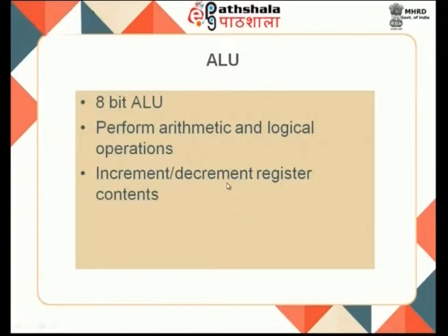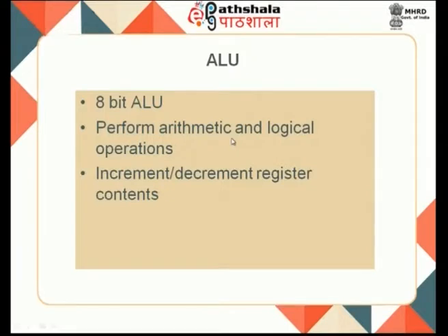outputs. Now, when I am looking at increment and decrement, not only arithmetic, we will be looking at logical operations also. Logical in the sense I will be doing AND, OR, NOT, all those operations can be performed when you are looking at your arithmetic logical unit. This takes care of your operands, processing, and results will be sent out. Other than that, incrementing and decrementing the register contents is also done by your arithmetic and logical unit. Sometimes the PC value gets incremented, sometimes the data available in your register gets decremented. This also can be done through your ALU.